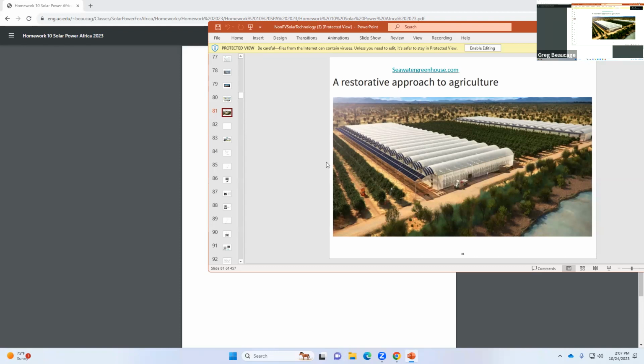But it's pretty interesting, like a science fiction place, because there are these big indoor halls with sand filters as far as you can see. It's really science fiction. Then you go to the carbon filtration. They put all the city's water through carbon filtration, which is like black pools, so you see this weird looking black water. And then they have their own regeneration of activated carbon. They have a big tower and furnace where they bake the carbon to get rid of the gunk in it.